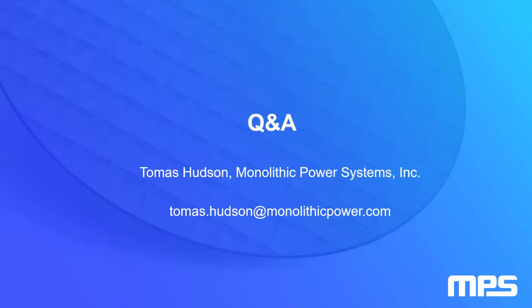Hysteretic control offers less stability in the steady state. It's more prone to being jittery. With COT, being able to modify the one-shot timer, we can maintain that fixed output voltage and reduce the error in the steady state to make it less dependent on noise in the circuit.